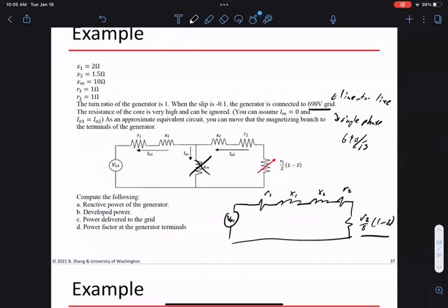So we really deal with this when we get to type 3. What type 3 does is, you can think of it as following: if I can inject a current that doesn't touch active power, but is sort of anti-phase to the reactive power part, can I inject this current with the right phase to cancel out the reactive power? That's the idea in type 3, and we'll see that design. Basically, it gives you another path for current to flow, and this current tries to cancel out the reactive power.